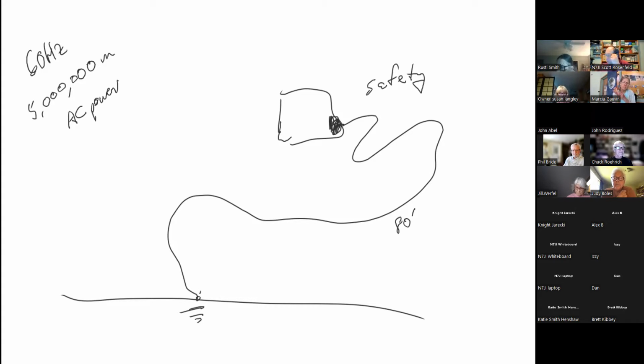So, compared to that, how long is this 80 feet? Compared to New York to California, how long is 80 feet? A drop in the bucket. So ground is really ground. Okay, but now, let us say that we're on a radio frequency band. We're still at 80 feet, but the frequency that we're on is the 10 meter band, which has a wavelength of 10 meters, which is about 33 feet.